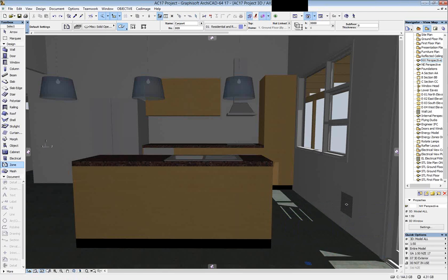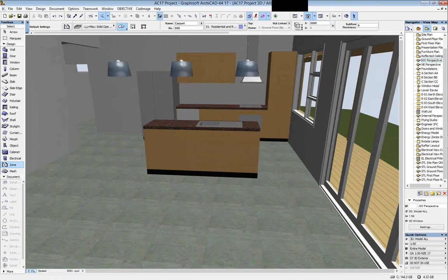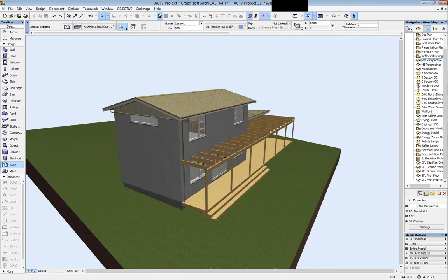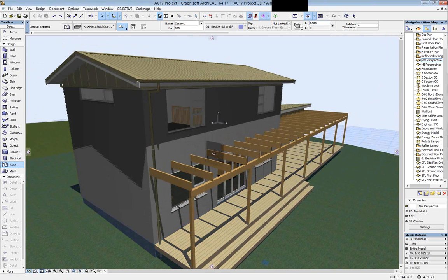So when you're in BIMx, you can save the file again, or you can share it to a portal. Now the saved file, this particular model here, is really, really small in terms of a BIMx file size. It's only 3 megabytes. So it's easily emailable to any client, and they can just open it directly from an email. And the other option is sharing it. It's basically like cloud storage. You share it online, and you can give a link out to your client, and that can be password protected.